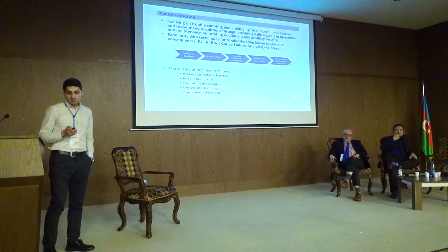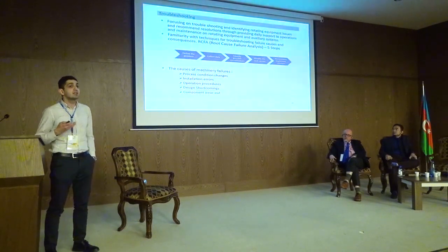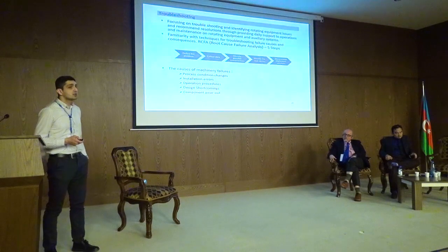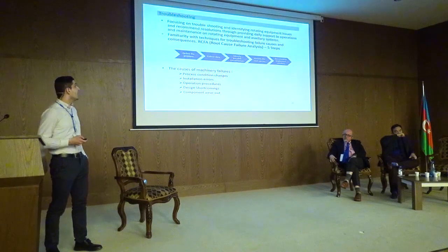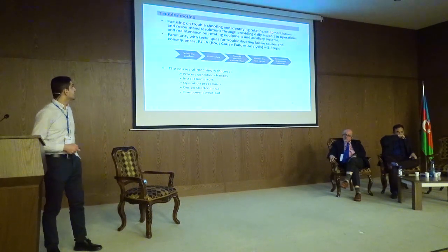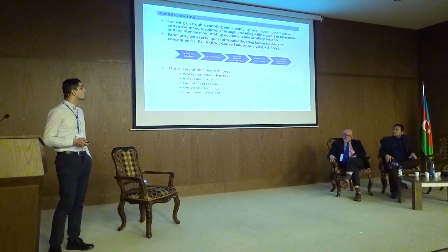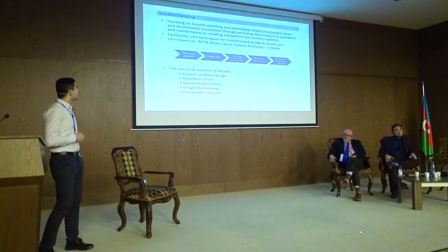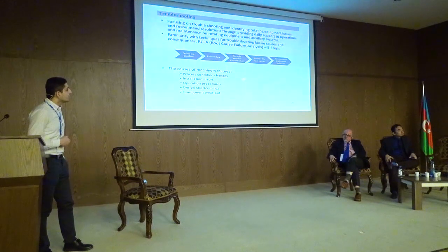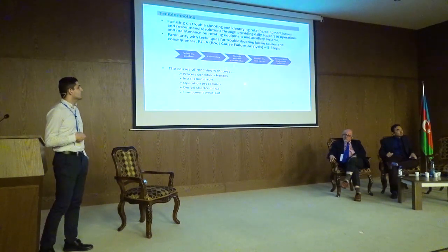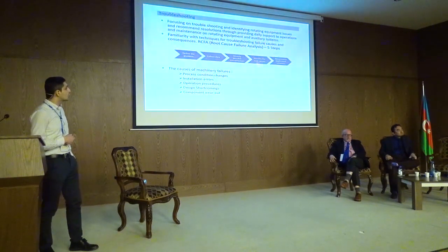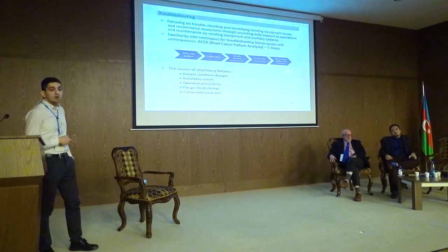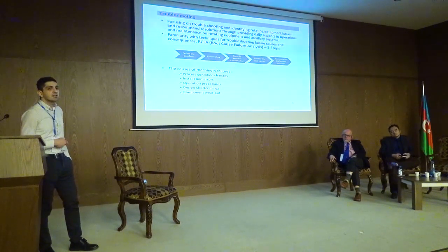Actually, the other important task of a rotating equipment engineer is troubleshooting. Troubleshooting is very critical. In order to troubleshoot, you have some techniques. One of the most widespread techniques is RCFA, root cause failure analysis, where you first define the problem, you collect data, you identify possible causal factors, and by eliminating the possible causal factors, you end up with a root cause. Then once you have found the root cause, you can start generating a solution, and then you can implement the solution. Yeah?